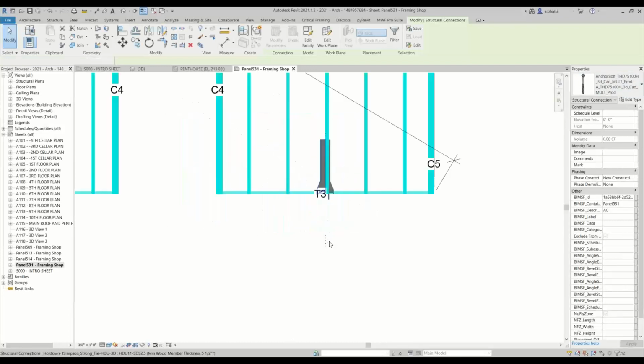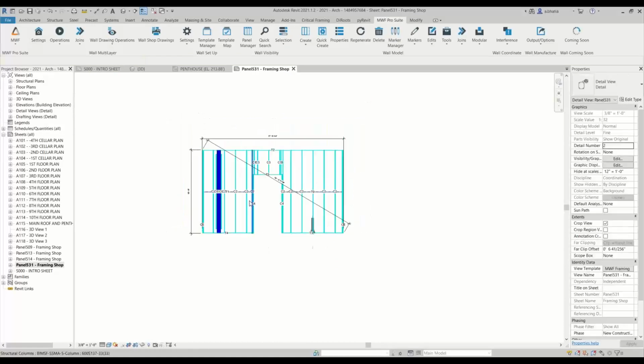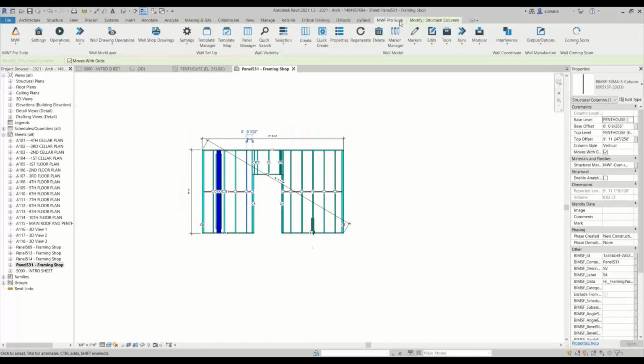So what I'm going to do is place our default anchor rods in the panel and recreate the shop quickly. But this is what ends up happening if we bring an anchor rod family into the project or get it from a manufacturer and we don't modify it. We just need to make sure we set the family up properly.